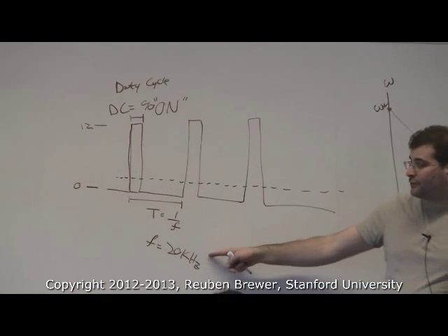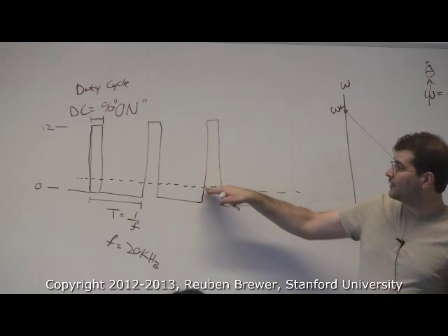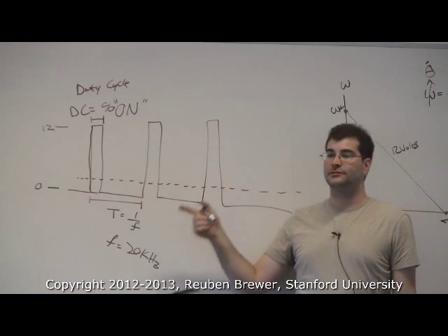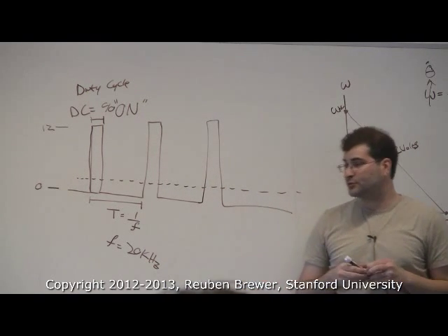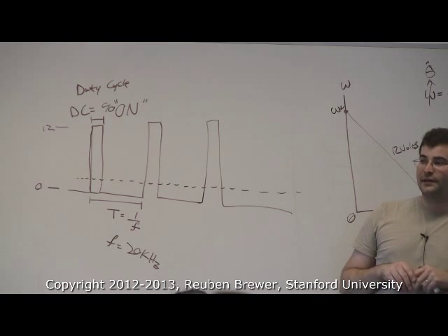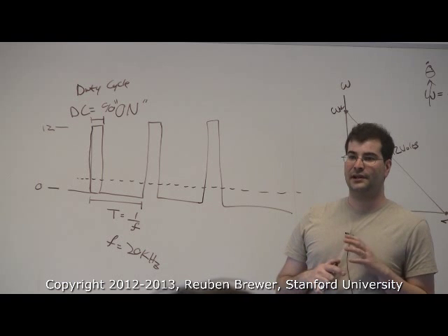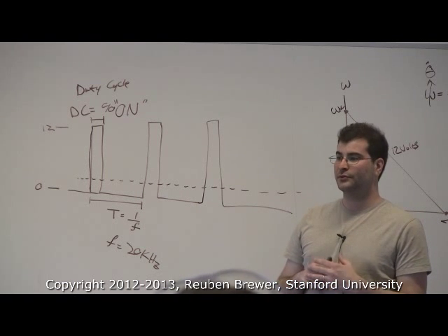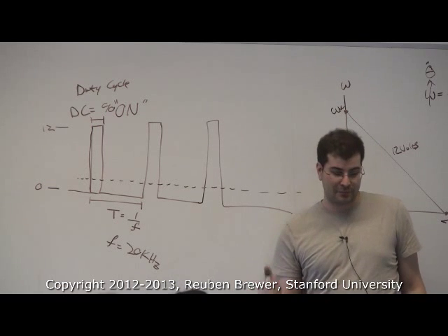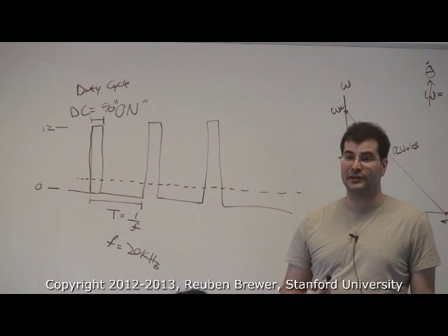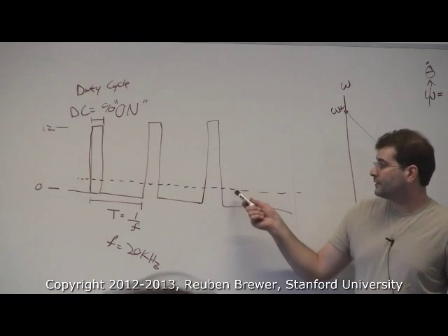As we speed up this frequency, it averages out, and it looks like, oh, I'm running at 10% of 12 volts, but it looks like it's constant, like we're not switching. But we have to be switching very, very quickly. Now again, this is a deep subject, and the 218ers have seen a lot more of this than we're going to even brush on today. I'm not trying to teach you all of it. I'm trying to teach you only the bare minimum practical stuff that really matters in my experience. Is everyone clear on this average voltage thing?